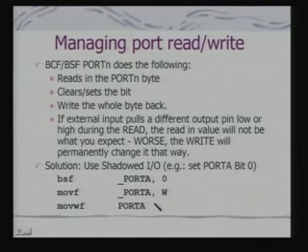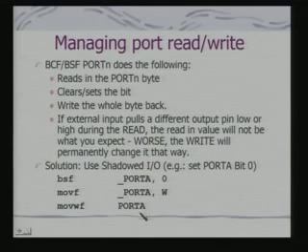And then what you do? You write onto W and from W you write onto port A. So, here what is happening is you are actually reading the data and whatever manipulations you are doing are on a shadow register. So, it is not being directly done on the port A register, only thing is that I am writing the final result onto the port A register. Okay. So, intermediate results will not affect the operation that you are trying to do.